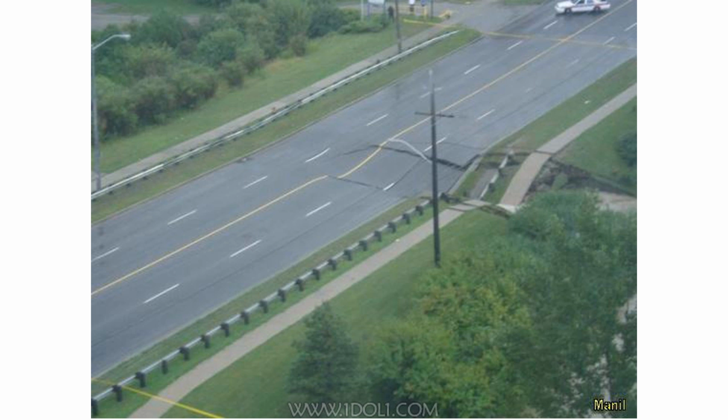And so if there's too much headwater, which is the case here, then it starts to wash some of the soil out. Like some of the really fine soil gets rinsed out as the water's seeping through.